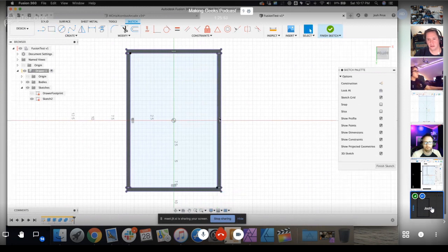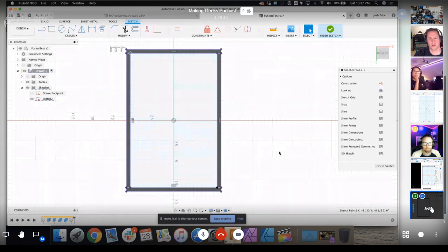Now, if the walls change shape, change length, width, thickness, my projection will change length, width, thickness. Therefore, this rectangle, which I just assigned to snap right there and to snap down there, will update length and width. Does everybody understand that? Projections are like an active silhouette. So if you're drawing against an active silhouette, everything will update with it.